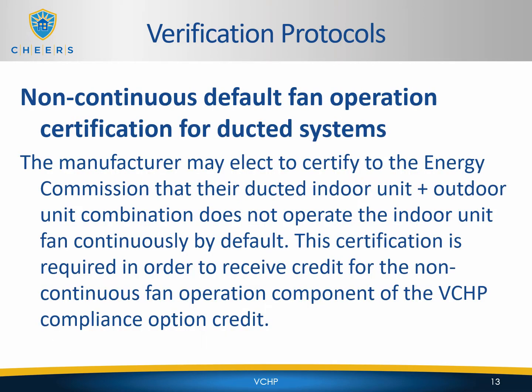Non-continuous default fan operation certification for ducted systems. The manufacturer may elect to certify to the Energy Commission that their ducted indoor unit plus outdoor unit combination does not operate the indoor unit fan continuously by default. This certification is required in order to receive credit for the non-continuous fan operation component of the VCHP compliance option credit.